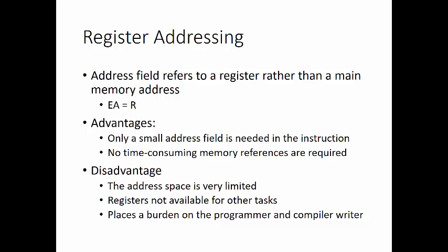An example of this is an intermediate result in a calculation. In particular, suppose an algorithm for 2's complement multiplication were to be implemented in software. The location labeled A in the flowchart is referenced many times and should be implemented in a register rather than in a main memory location.